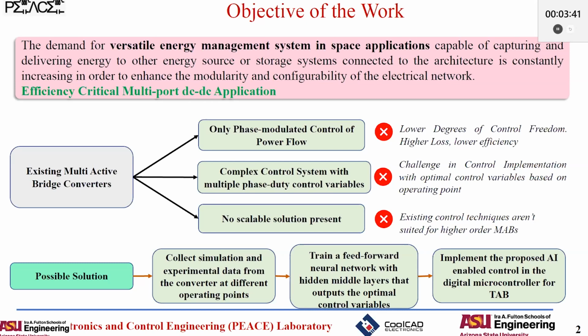But the problem with this solution is that the usage of multiple bulky transformers or other magnetic components increases the weight and volume and reduces the conversion efficiency of the whole system. Therefore, in this particular scenario, we propose multi-active bridge, in short MAB, converters, that are deemed promising solutions to enable multi-directional power conversion over a wide range of voltage gain and loading conditions.